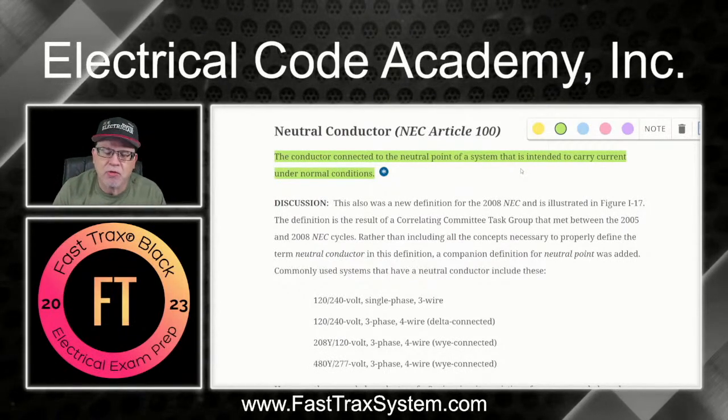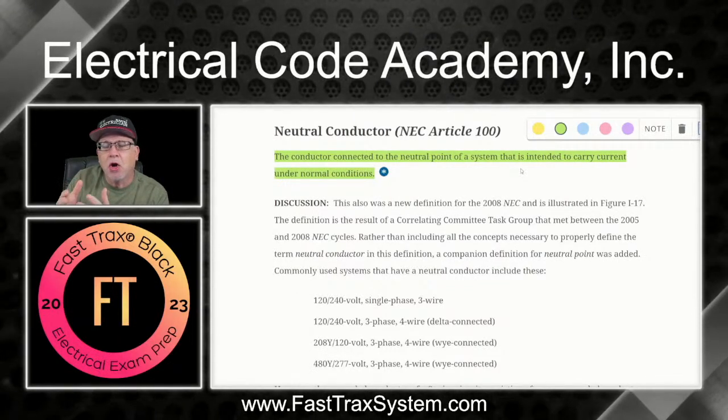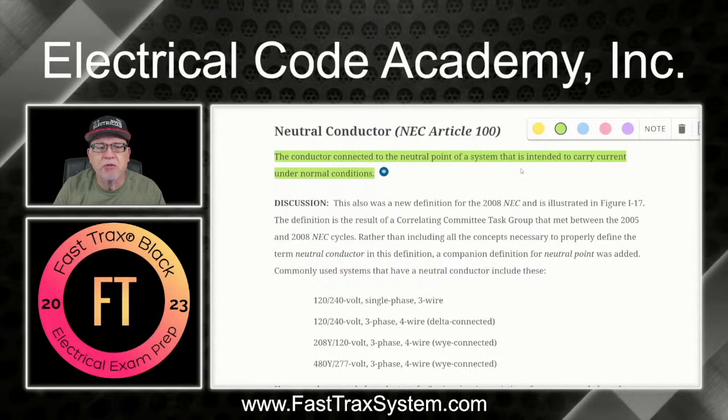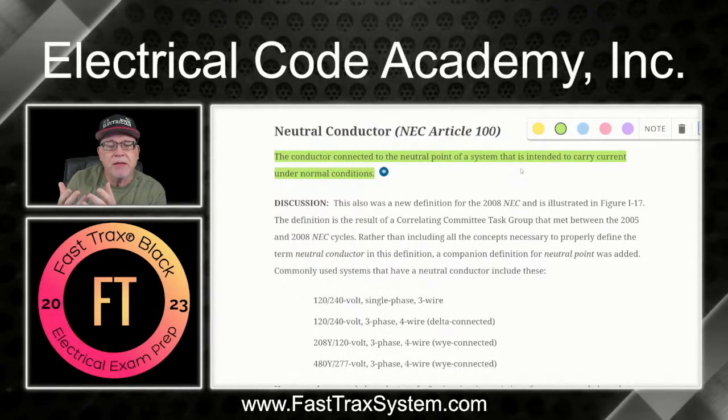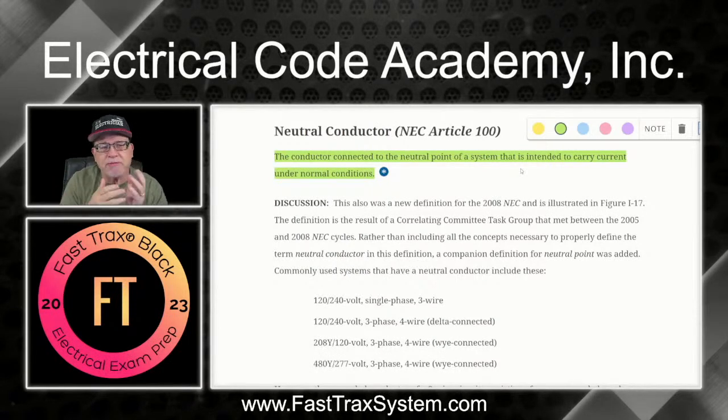And it's why it's so important for us to talk about improper case to neutrals downstream, where you connect the equipment ground to the neutral conductor improperly, because what you're doing is imposing current onto the metal parts, which are connected to the equipment ground. The equipment ground is serving dual roles, right? It's not only giving you a reference to Earth, but it's also being used as a bonding component.